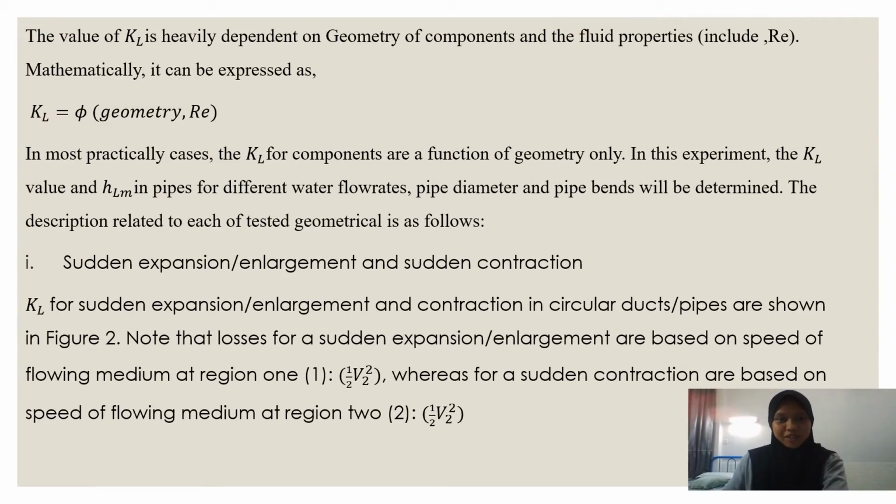So in the theory for this experiment, to determine the KL value, the value of KL is heavily dependent on the geometry of the component and fluid properties. We include the Reynolds number, Re. Mathematically, it can be expressed like this. In most practical cases, the KL for components is a function of geometry only.